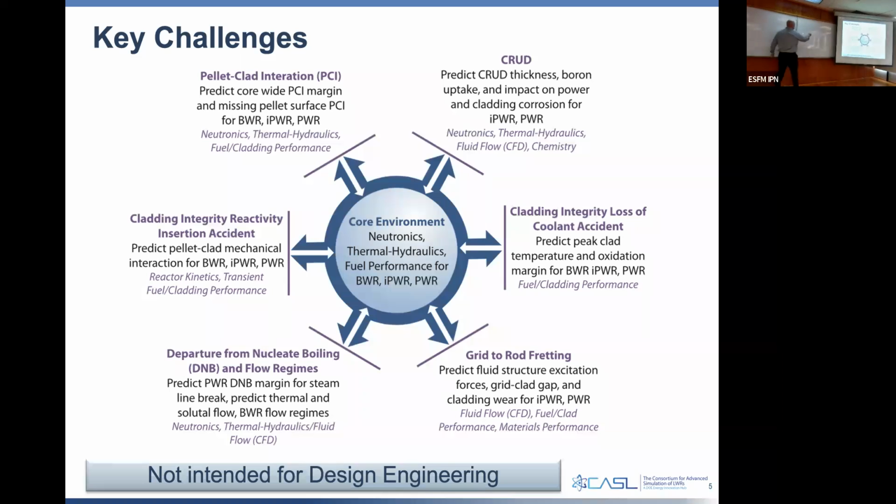So if the original pin were sitting in the grid spacer and had some springs helping it lock in place, if this cladding shrinks, then you get a gap around those springs. And now that pin can vibrate back and forth, start hitting those springs and wear a hole in it. So understanding the global effect on how that dimension changes in the fuel comes into play.